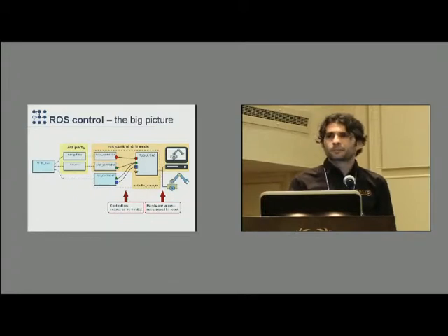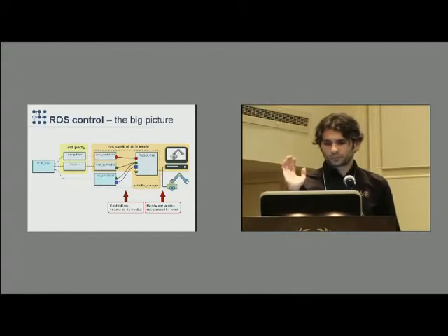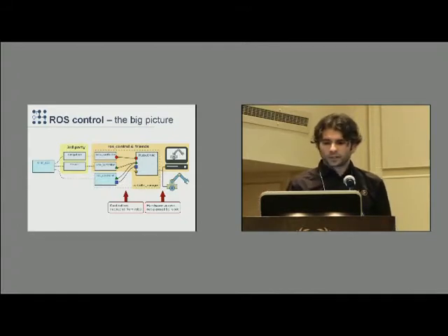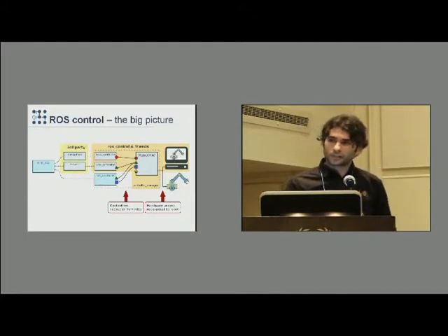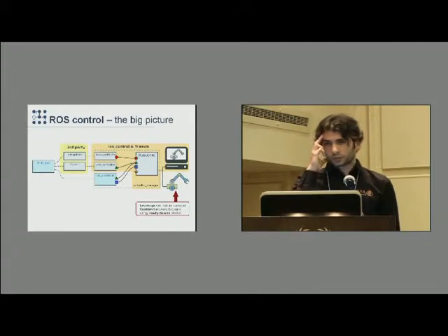Important aspects to highlight here is that this robot hardware tries to decouple hardware access. So you don't expose how you talk to your robot. And this is really important. Another layer of decoupling is that controllers and your robot hardware abstraction are decoupled, so you can develop them independently and in isolation. So this enables you to share and mix and match controllers. When you want to write your robot backend, there's a possibility to leverage out of the box a simulation backend. So this is good.